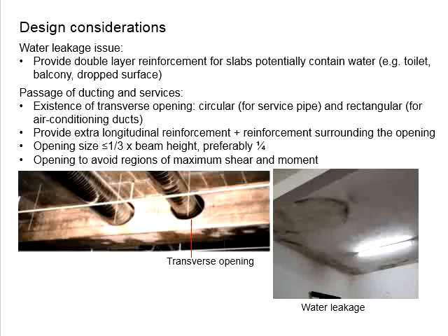And normally this extra reinforcement is going to be quite extensive, trying to compensate for the losses in capacity due to this transverse opening. Most likely you know which beams are going to have this transverse opening, as observed from the architectural drawing, which shows the pathway of the piping as well as the services.